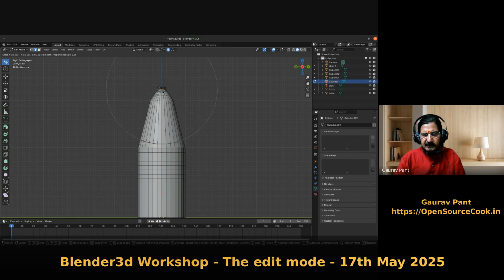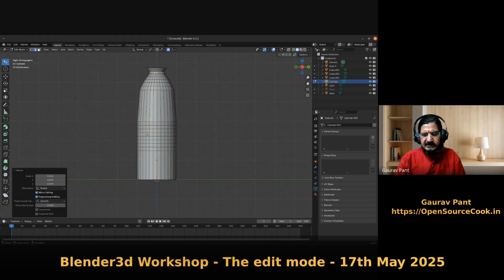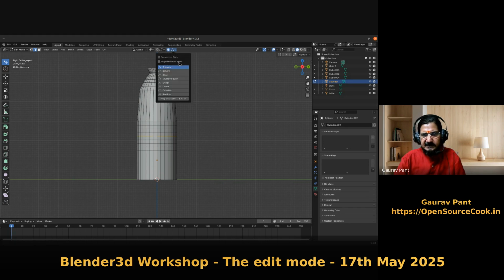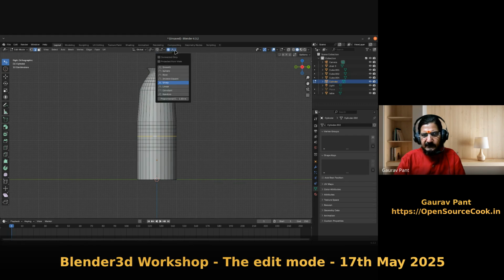Like if I wanted a bottle where this is the head area of my bottle. Similarly, I will do a loop select over here by Shift click, and I will scale this. Now this time we'll change the influence to sharp, and let's see what happens. For the sharp influence, we are getting a different kind of shape. So you could scale this and decide on the influence type.